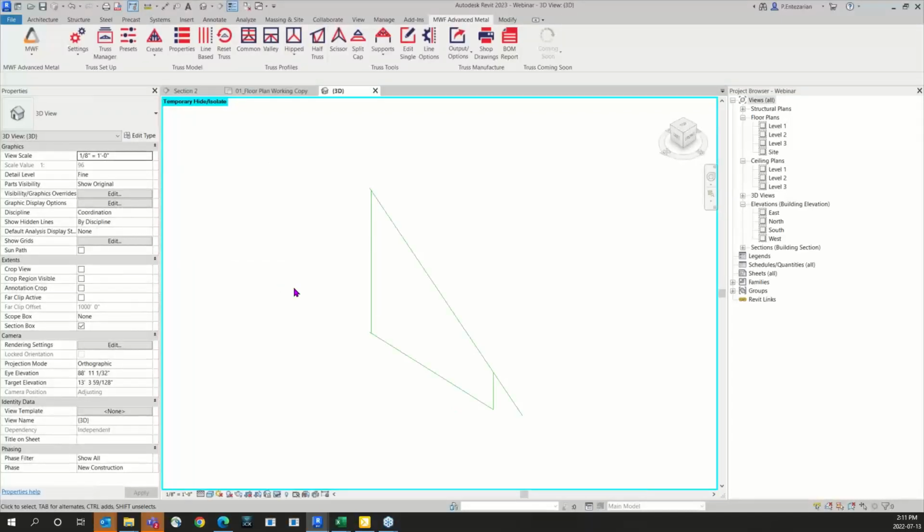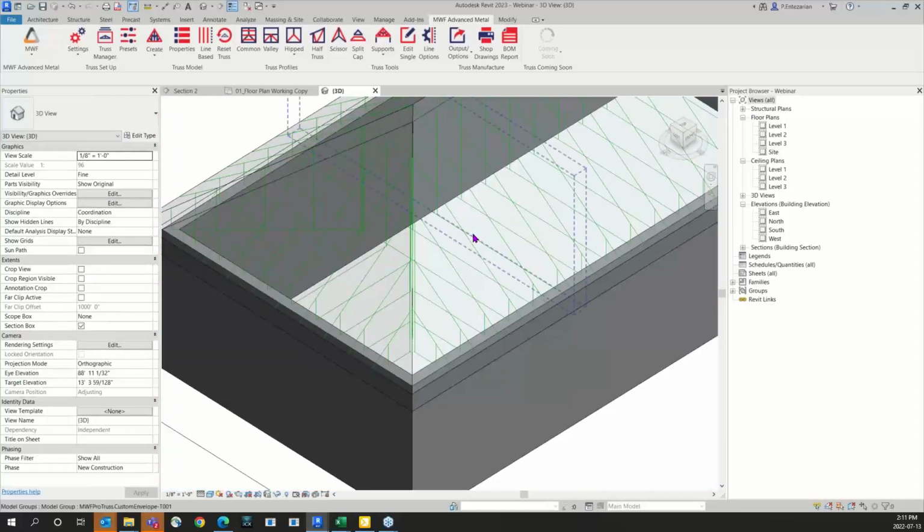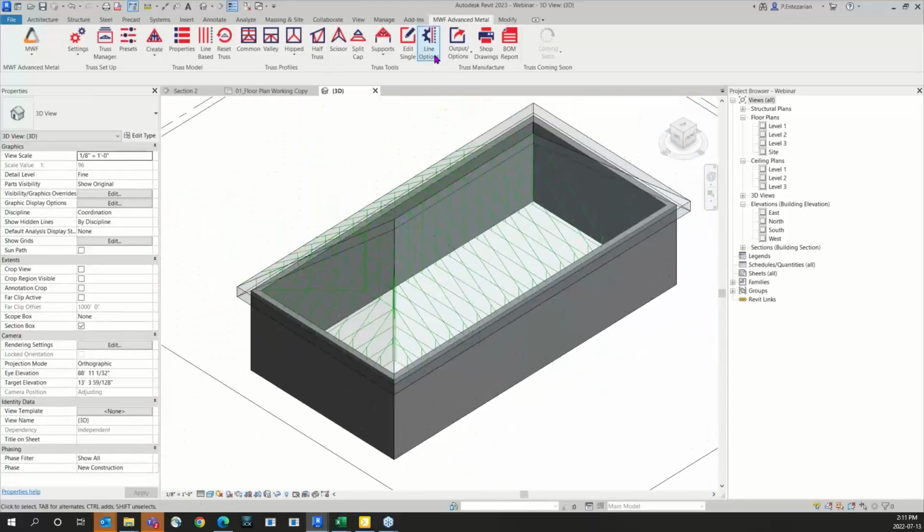In this case, if you prefer to create oddball envelopes in your project, you can do that. You can use the line options command to tag those members, and you can easily add auto truss connections for those oddball envelopes. Let's go back to our project by typing HR. So this was the first new option that we have added here.